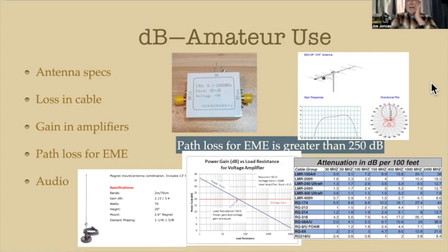Now, antenna manufacturers use that. They should not, because a dipole was the only practical thing out there to start from. But you get, I think it's about 2.3 dB for a dipole over an isotropic pretend antenna. The specs that you get when you go to purchase an antenna or you're searching for one are in dBi.